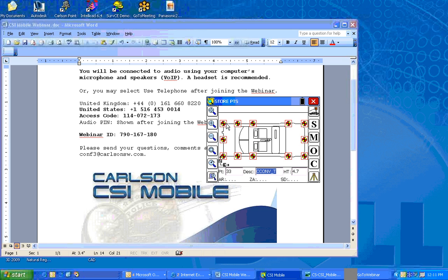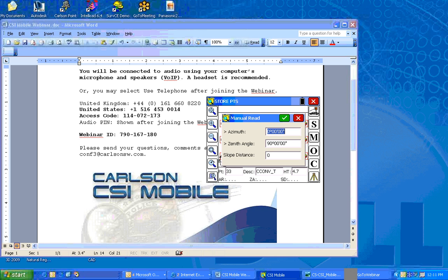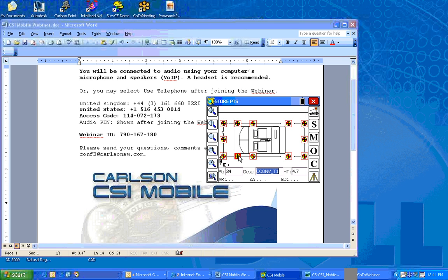And we're back to this. So let's just say we get the right rear tire. And I'll say that is an azimuth of 30 degrees, slope distance of 20 feet from where I'm set up. And just by chance, for orientation, I'll just go across the car and get the left front tire, and hit enter.